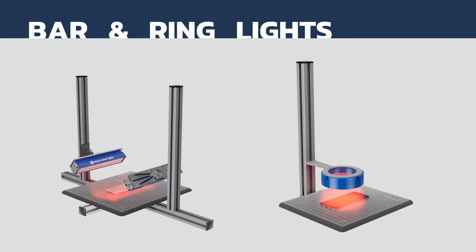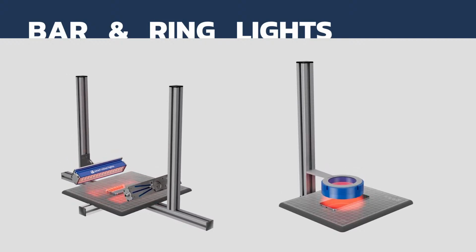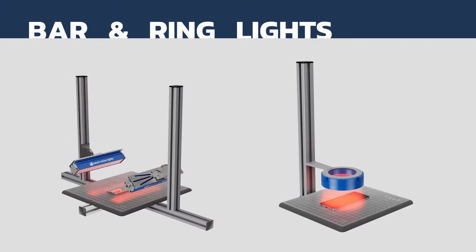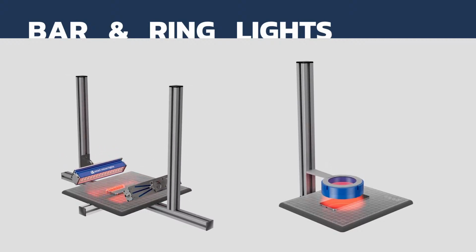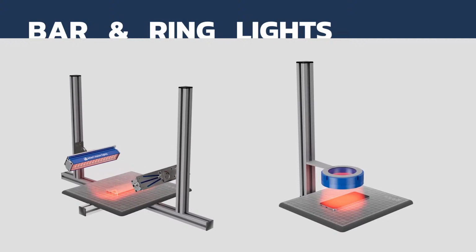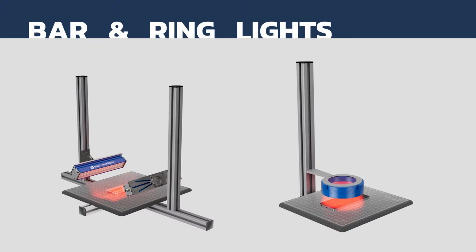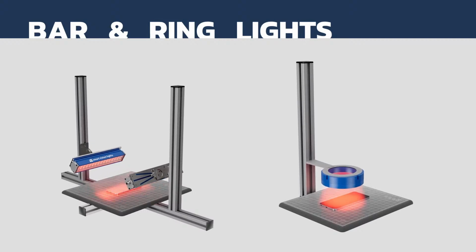The bar lights then are able to be positioned low and to the outside, but again, it's really useful to be able to tilt them because, again, we want to find that right angle where the rock skips off the pond, if you will, or the photons off the surface of the object we're inspecting. And by tipping it in and out, you can get them exactly right and get them balanced as well.